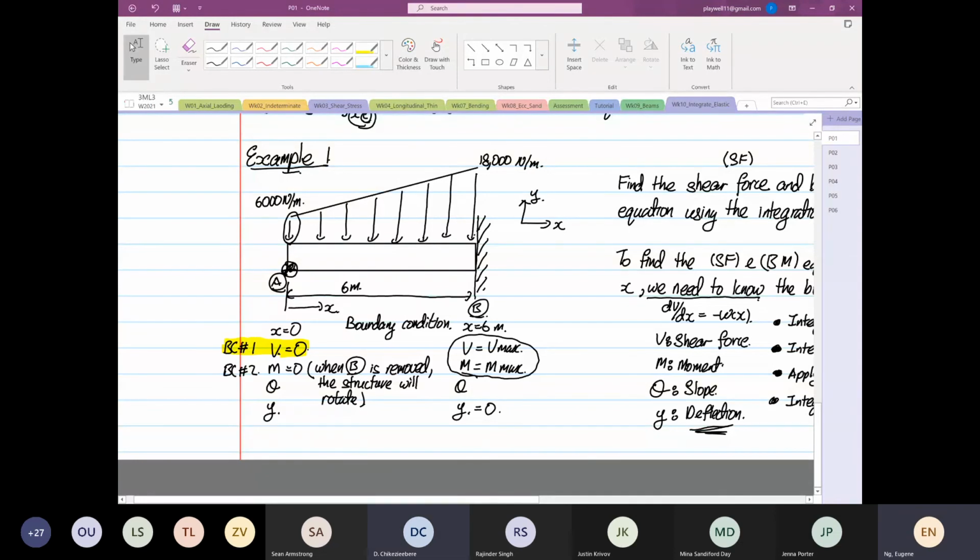I repeat again. Why do we think? Yes. Because it's cantilever. So what if it's cantilever? Why is it maximum at point B? Because x is maximum at B, because bending moment is load multiplied by distance. No. Because that's where your failure would occur? Well done. Okay. Because failure will occur over there.